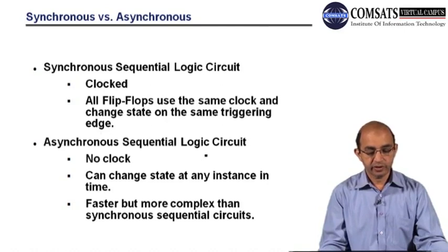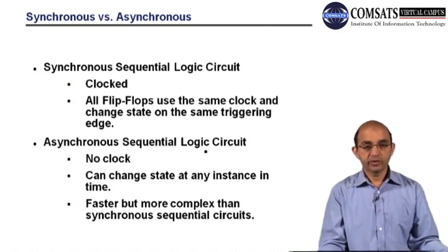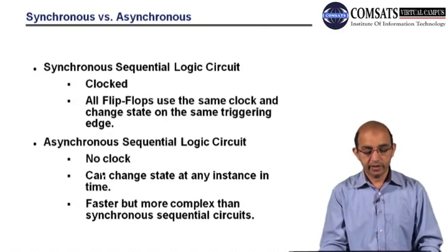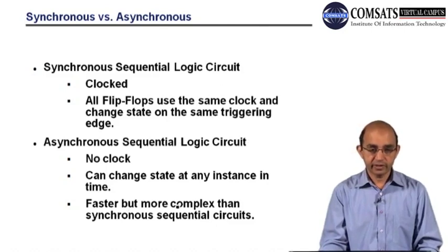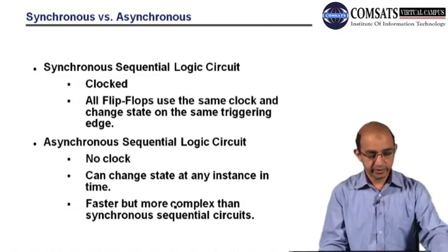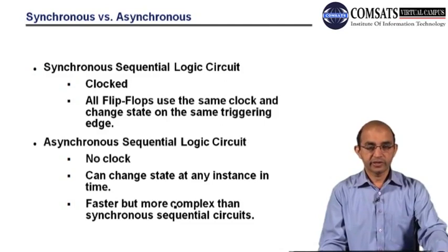In asynchronous sequential logic, there is no clock, and the state can change at any point in time. It's faster because we don't have to wait for the clock, but it's more complicated to design. So there is a trade-off: asynchronous is faster, but more complications are involved regarding the design.